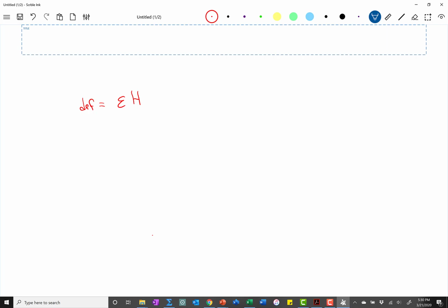And of course, strain is equal to the stress divided by the modulus of that material. This is where we always get the famous equation PL over AE when we talk about deformation of a steel bar, or a wood beam, or those kinds of things.